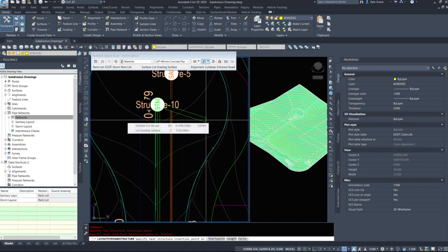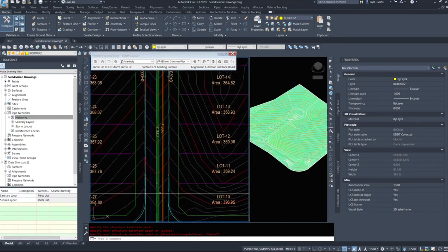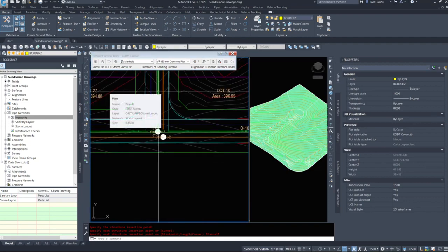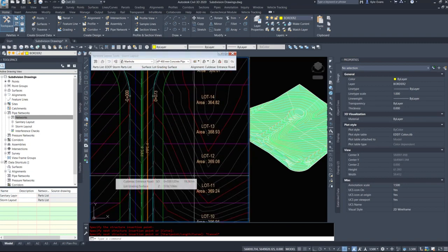Now, we do not have a catch basin at the top here. So why am I putting a manhole into my cul-de-sac, a storm manhole? We have no water flowing from here into this manhole down. What we do need to worry about in most areas is groundwater. There will be groundwater. You're going to have weeping tile around any house, and your foundation is generally 2 to 3 meters below ground.